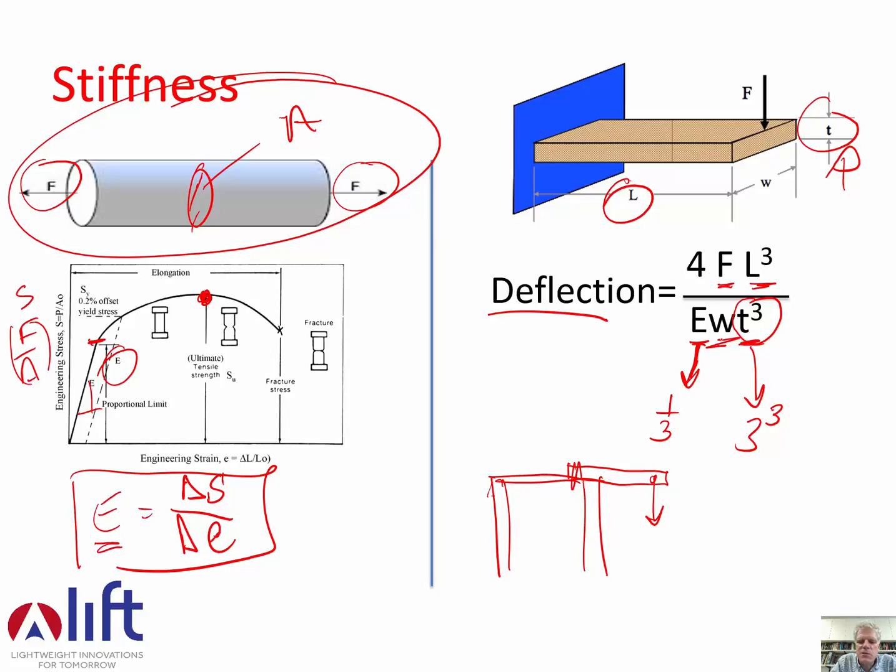So aluminum is intrinsically less stiff, but because you get so much more of it, it behaves as if it's stiffer in something like bending. That's why we like to make aluminum trucks. That's why they can be actually lighter weight, quieter, all that kind of good stuff.